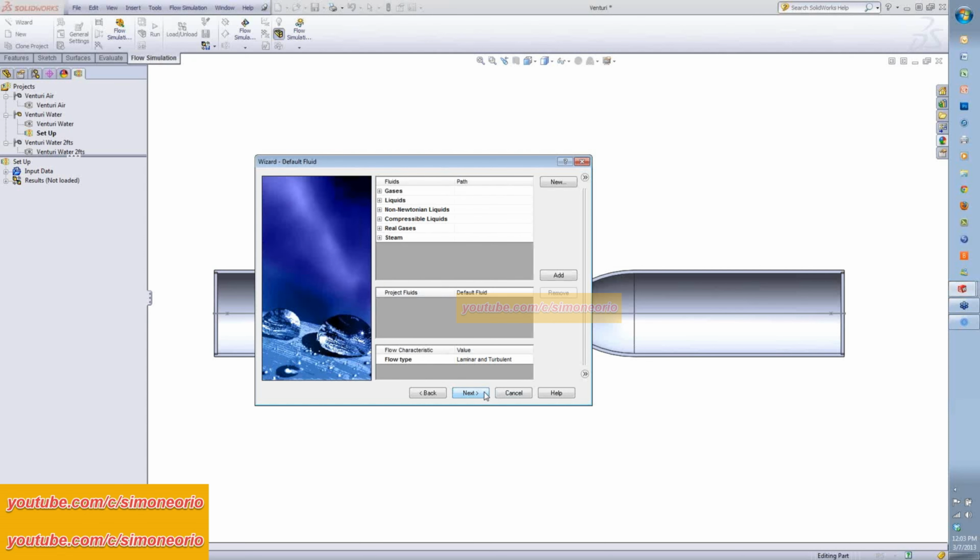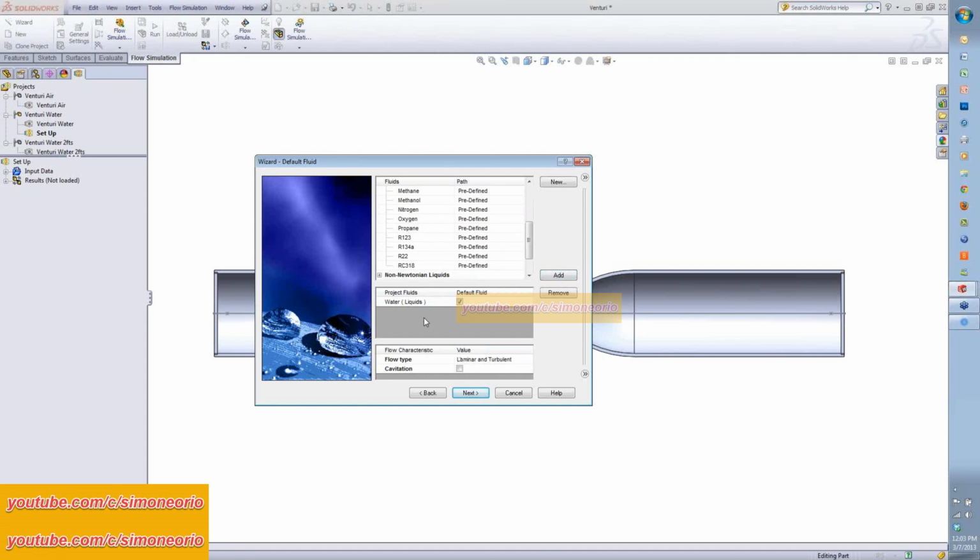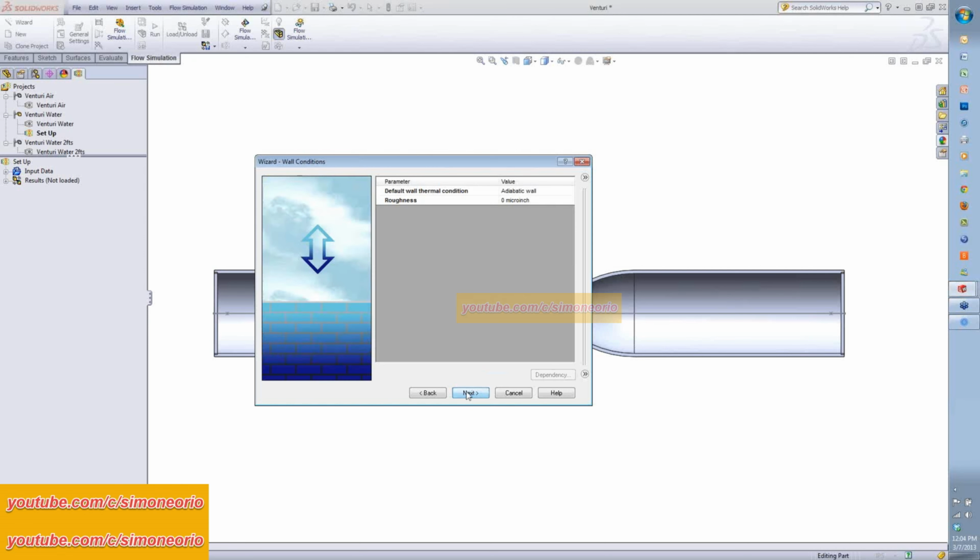At this point, I want to tell the software what liquid we want to use. In this case, I actually want to use water, so I'm going to be utilizing a fluid. I'm going to add that in. All of our properties of water, such as the density, viscosity, things like that, are all housed inside a database, which I will show you. I want laminar and turbulent flow. We can handle just laminar or just turbulent or both. So I actually want both to be solved.